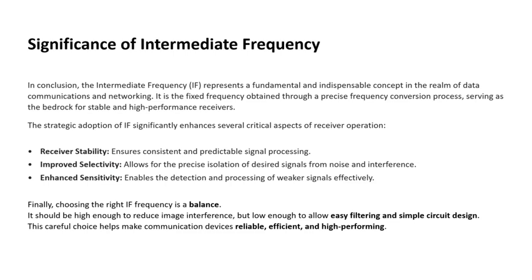Choosing the right IF is always a balance: high enough to reduce image interference, low enough to allow easy filtering and simple circuit design. Because of this balance, the communication system becomes efficient, reliable, and high performing.